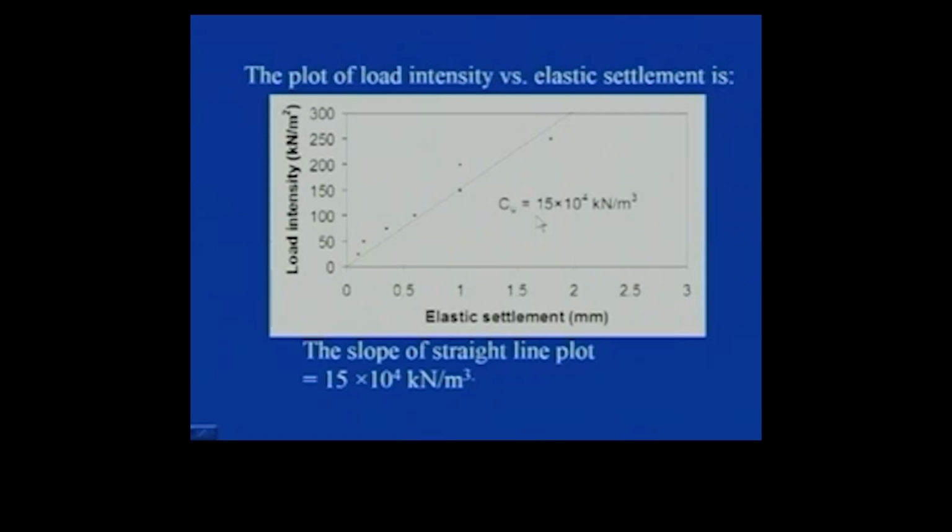Now, as we were discussing last time, when you are finding out these constants in the field and then applying them in case of a foundation, you have to apply some correction measure, because their values depend on the contact area of the block foundation and the soil. The test plate is of a definite size, like 30 centimeter by 30 centimeter.